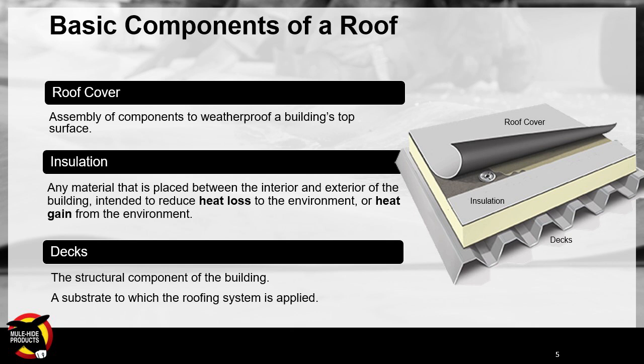Yeah, so all different options when you're talking about low slope roofing. Tim, let's talk about the basic components of a low slope roof. Yeah, and hopefully I can explain this how I learned it. I came from zero experience in the roofing industry, so I think I have a pretty good way of doing it. I'm a big foodie, so I like to relate a lot of things to food, and I like to think of a low slope roof as an open face sandwich. It's just that easy. So you have three components. You have your deck, which is the actual top structure of the building. I like to think of it as like a nice hearty bread. You're going to have an insulation or cover board on top, and that's going to be your meat of choice. And then finally you have your roof cover, which is going to be your membrane, your liquid applied, and that's going to be the slice of cheese. So if you can remember an open face sandwich, that's as complicated as it gets for low slope roofing.